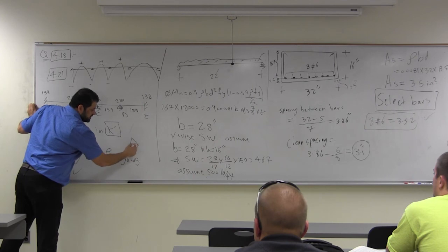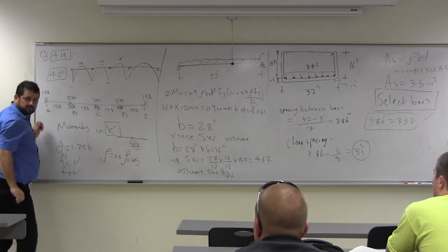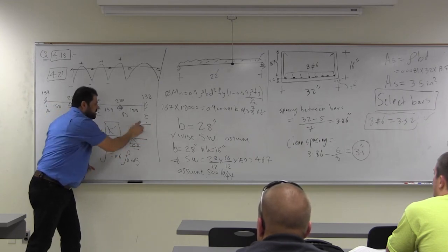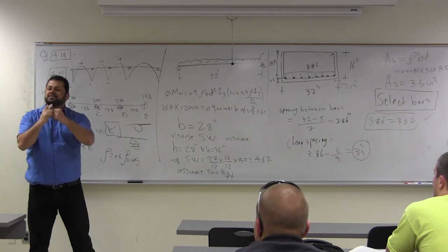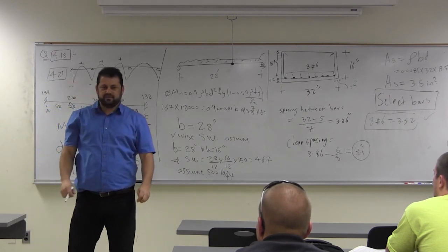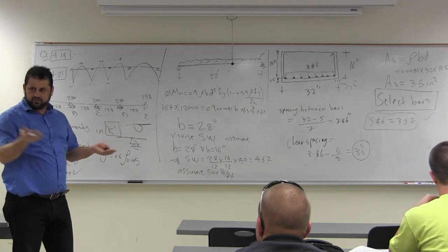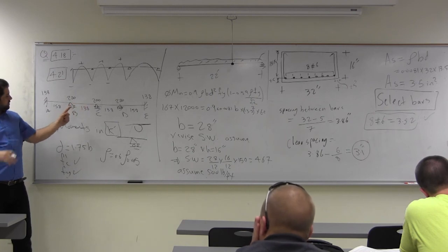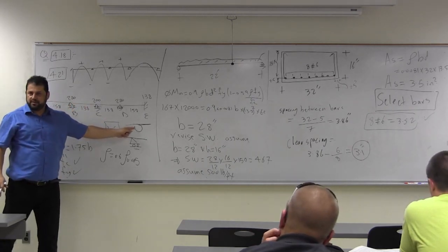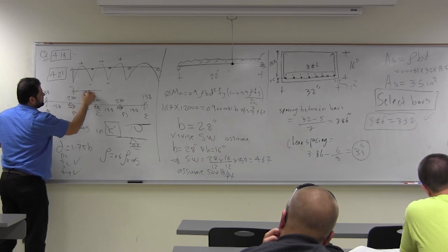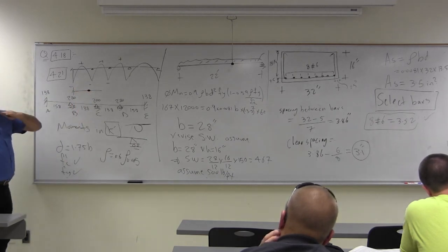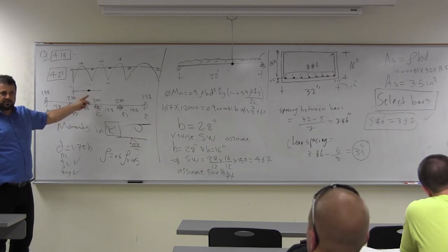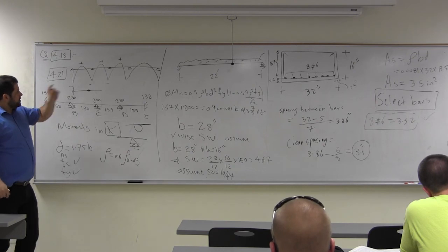Paul, see this support here? The beam is going over it. So look, that's the support. The beam is over it. It's not broken into two pieces. It's not an internal hinge we're talking about. The beam is one segment. It's just sitting on the support. Whether we draw it this way or that way, it's a roller. The internal hinge, you see it like that. It means the beam is two segments. It means at this point we release the moment. It's free to rotate. Good?